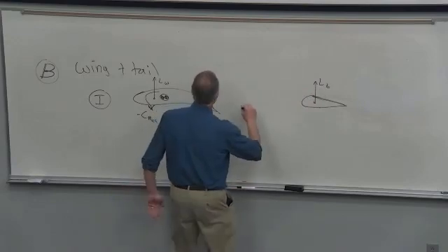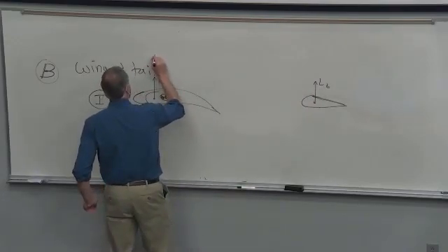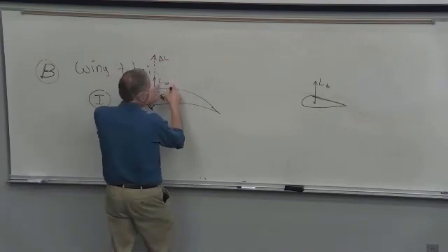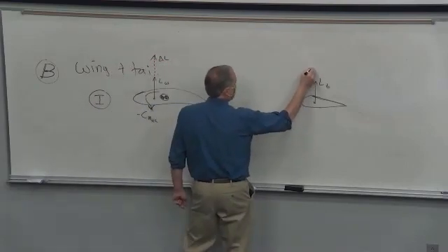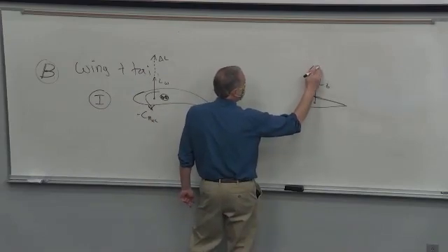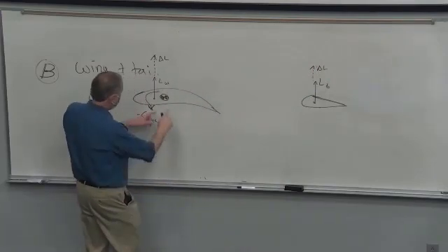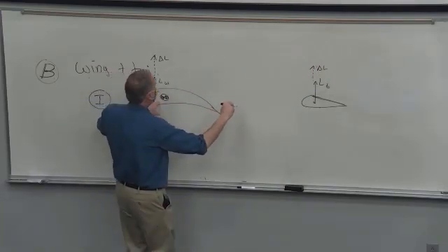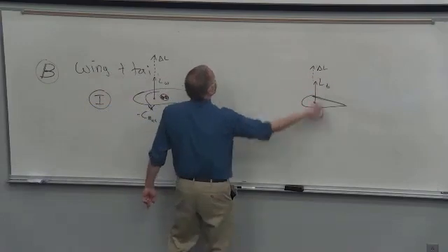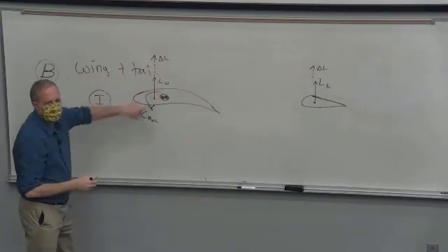But if we put the tail far enough back, when we get a gust, this lift goes up and this one increases. It may be really small, but then we get a significant change in the lift here. And if you put the CG and the tail far enough back, this creates enough of a nose down to counteract the nose up here, and you get stability as well.